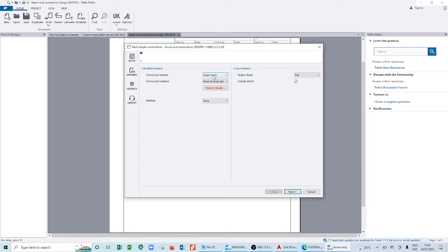So now meaning I have options of either using an angle cleat. When I click on this, it will give me, do you want to use the angle cleat or do you want to use the end plate connection? Now end plate connections, you're going to either machine cut or you fabricate them yourself. So meaning mine, I'm going to choose, I want to use the end plate connection.